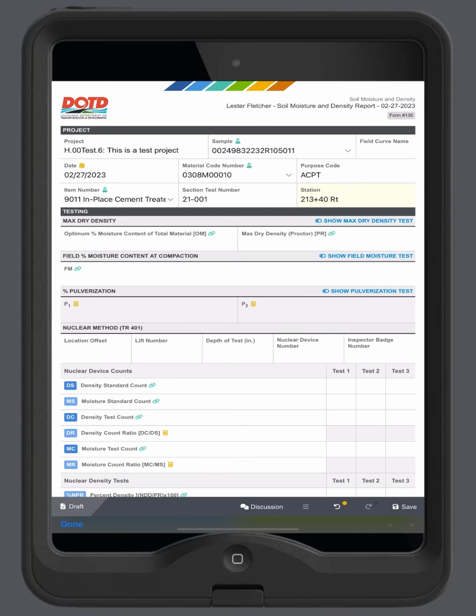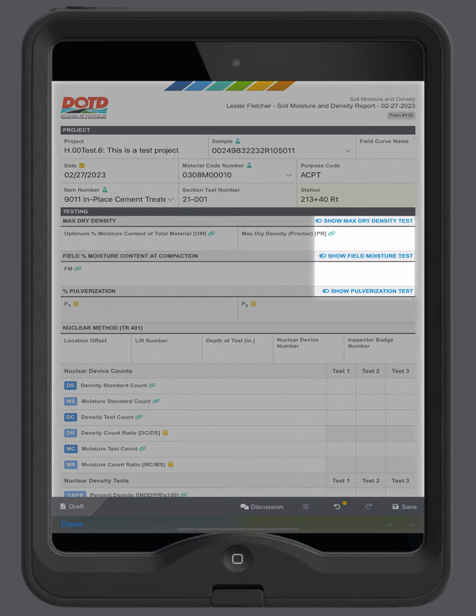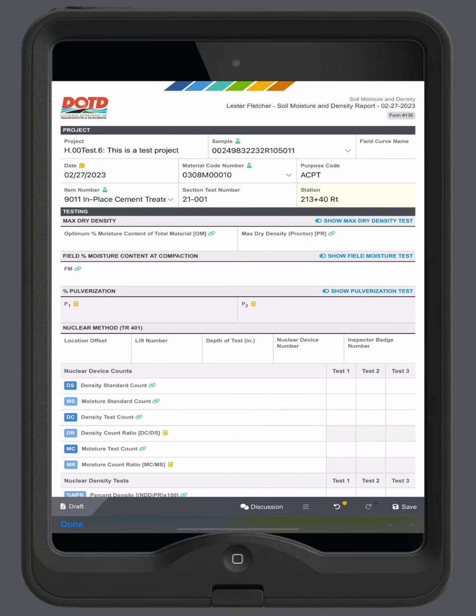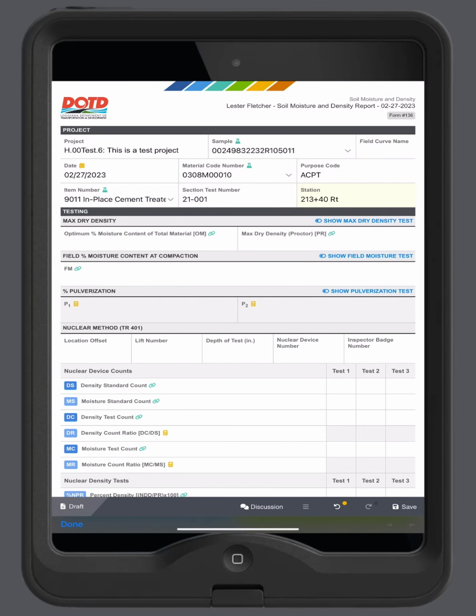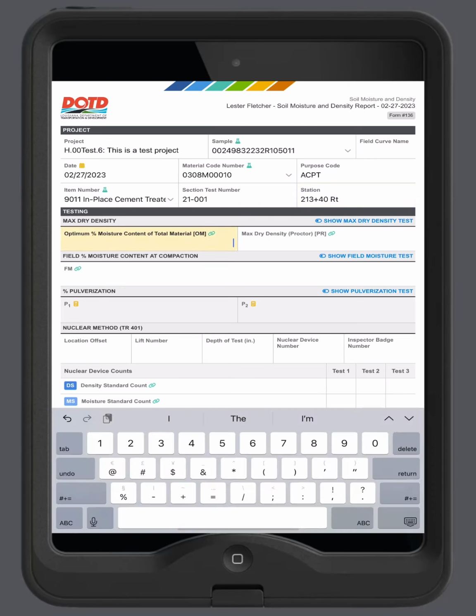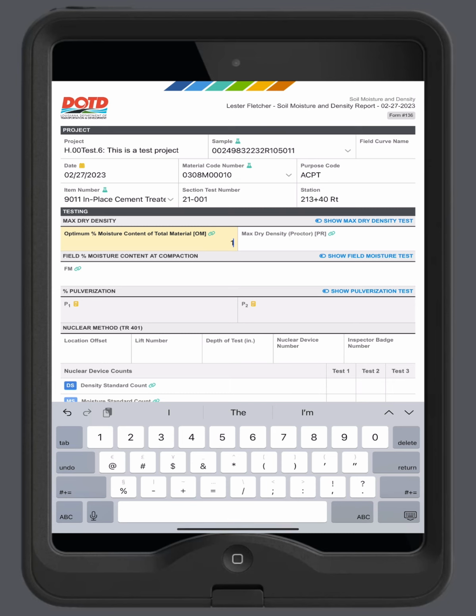Alright, let's get into the test section. You'll find sliders available to input your max dry density, moisture, and pulverization test results. Keep in mind that the nuclear method is always open since it is the most commonly associated test with the form. I'll be showing you how to enter max dry density test information towards the end of this video, but for now, let's work with some known values and enter our optimal moisture content and proctor into their respective fields.